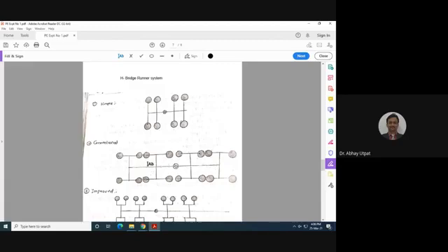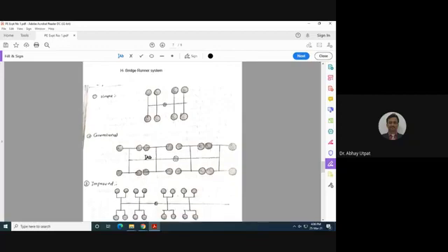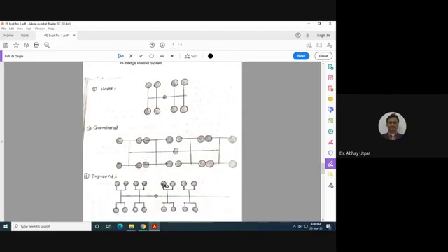So 1, 2, 3, 4 branches are there and again 2 sub branches. It is improved design again. Number of cavities are increased. Check difference between first and second and third. Rebranching, more branching will be provided. All these types are called as H-bridge runner system.